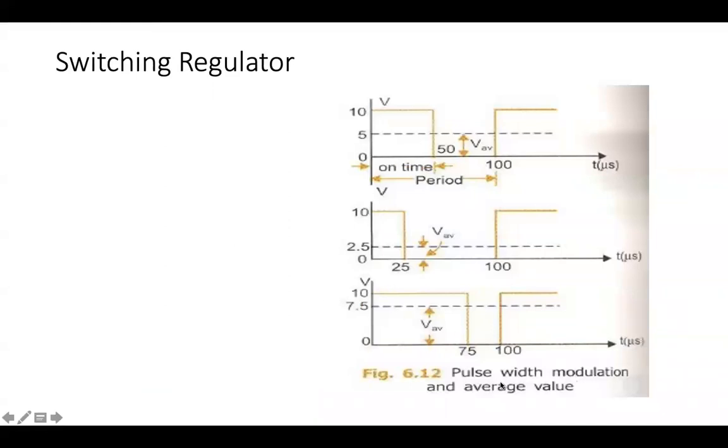Now, based on the pulse width, remember I was telling you about the pulse width, how the on period and off period change. Accordingly, we can increase or decrease the speeds. This is what I have put up here. You can see that the on time and off time are both equal, 50-50. It is on for 50% of the time and off for 50% of the time.